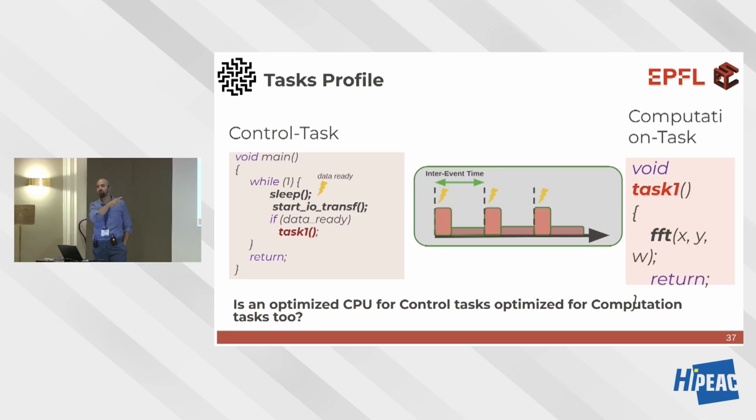No one is talking about this guy? I would probably not have floating point on the control. Yeah, for example, this guy won't have the floating point unit then? We might even remove some registers on the control if it's sufficient. Exactly, you can use the RVE extensions on RISC-V, still within the RISC-V context. So having fewer registers here. We can have a very small data path for the ALU.